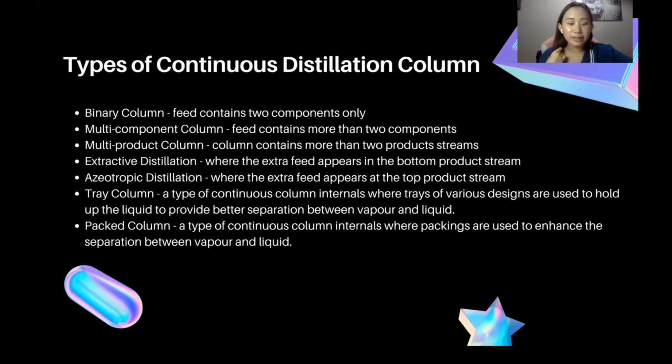So for the extractive distillation, this is where the extra feed appears in the bottom product stream, while for the azeotropic distillation, the extra feed appears at the top product stream.